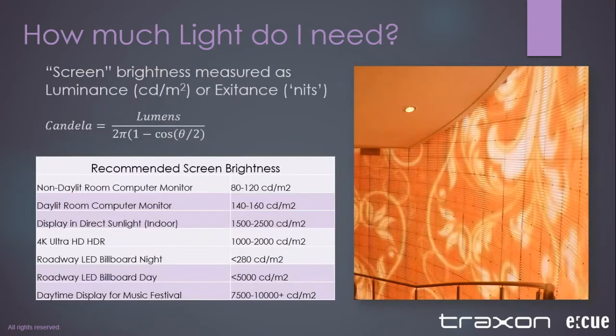This, though, is really a luminance or an exitance application where we're looking at fixtures. You may need to take the lumens off the spec sheet for the fixture and figure out how many peak candela you're getting off of it if that's not reported on your spec sheet. This equation in the middle helps us do that.